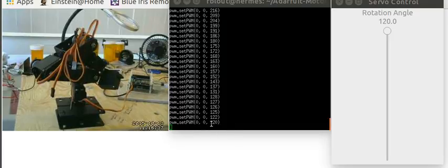If I tried to go to 110 by changing the min value in the program, the motor will hum, and I could very easily strip out the gears. So you need to proceed carefully.